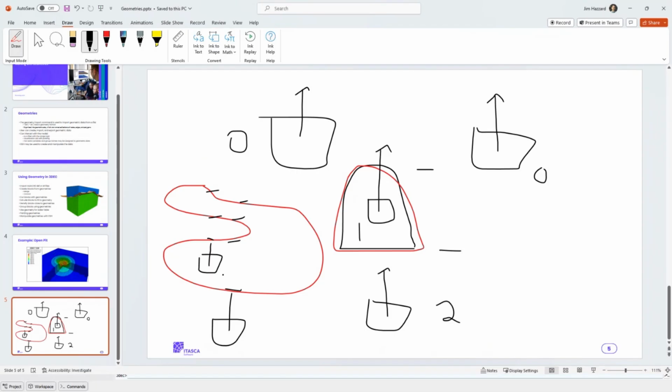So the syntax is kind of weird, but it actually works. If you just say count odd, you will identify all of the blocks that are inside of that geometry. There actually is a keyword that's just inside, which is more intuitive, but it only works if you have a completely enclosed volume. So it checks to see if you're completely inside of something that's completely enclosed.